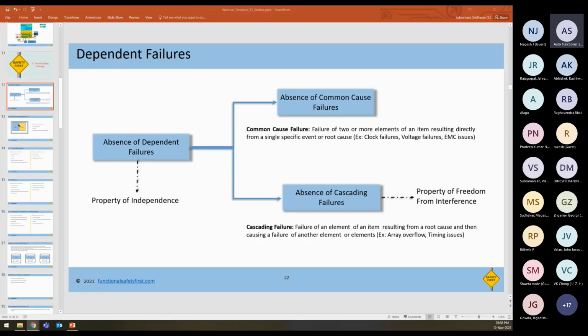Why do we need a health manager when we have a watchdog in place? The watchdog, like a hardware watchdog, whether it's a windowed or a non-windowed watchdog, cannot really detect the various possible timing faults in a system. Let's say we are not petting the watchdog within the required timeout, whether that's a windowed watchdog that has a lower and an upper threshold, or a normal watchdog with an upper threshold. If it doesn't get petted within that time, it will time out.